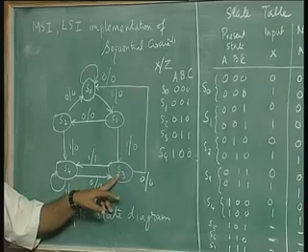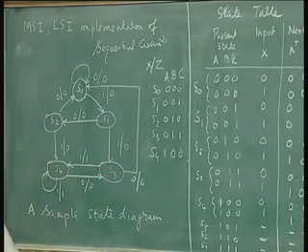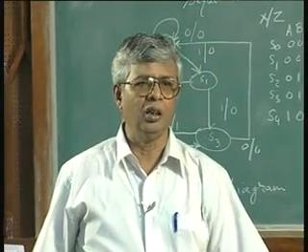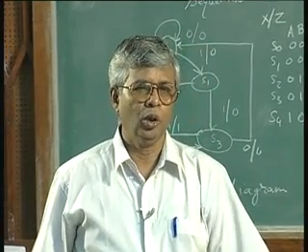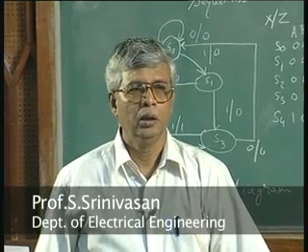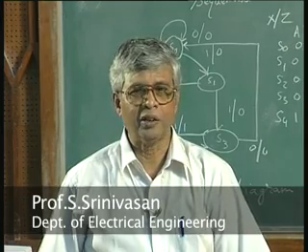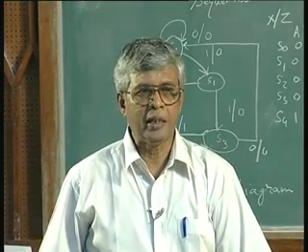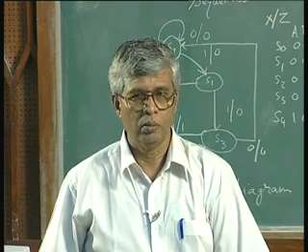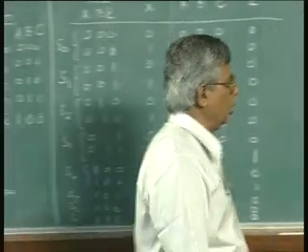In a Mealy machine, we are saying the present state alone does not determine the output; the present state and the input determine the output. So, the output corresponds to the present state, not to the next state. This is a confusion sometimes people have, and some of the books do not explain this very well. It is the present state output we are defining. Is that clear? Right. Good.